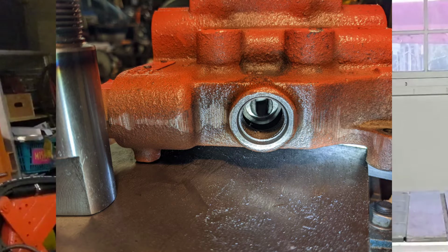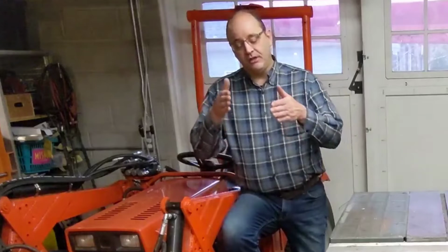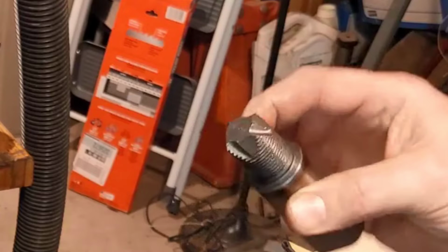I'll be making both these tools because if they are available for purchase, they're going to be outrageously expensive. For the tap, I used an old trick that I found on the web. To create any tap, you can just machine the male threads that you want onto some high carbon steel, then heat treat the steel, and then grind 4 bevels that effectively put a taper onto the leading edge of the threaded portion. Each of the corners of those bevels becomes a cutting edge to carve out the thread channels.